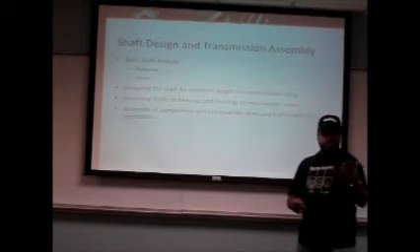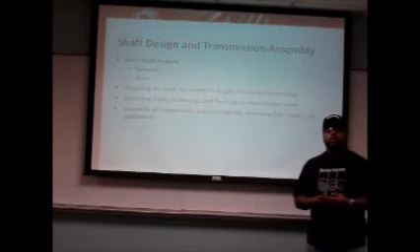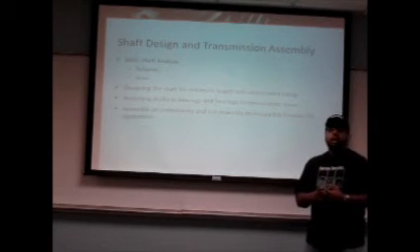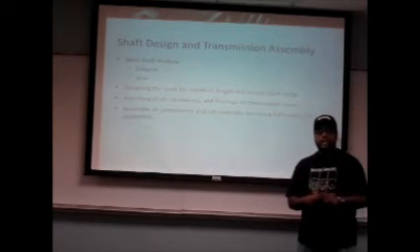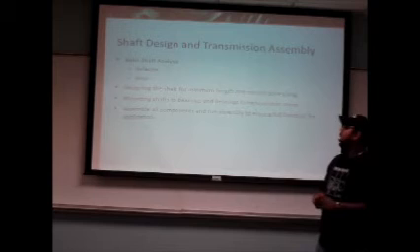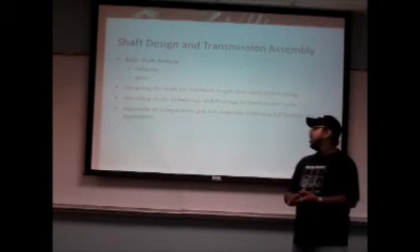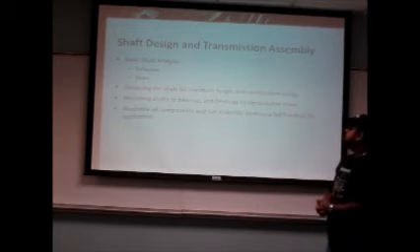In our shaft design, based upon the bore diameter of the bearings, we chose the diameter of the shaft on steel alloy 4140 because of its corrosion resistance, its manufacturability, its machinability, and its wear resistance.